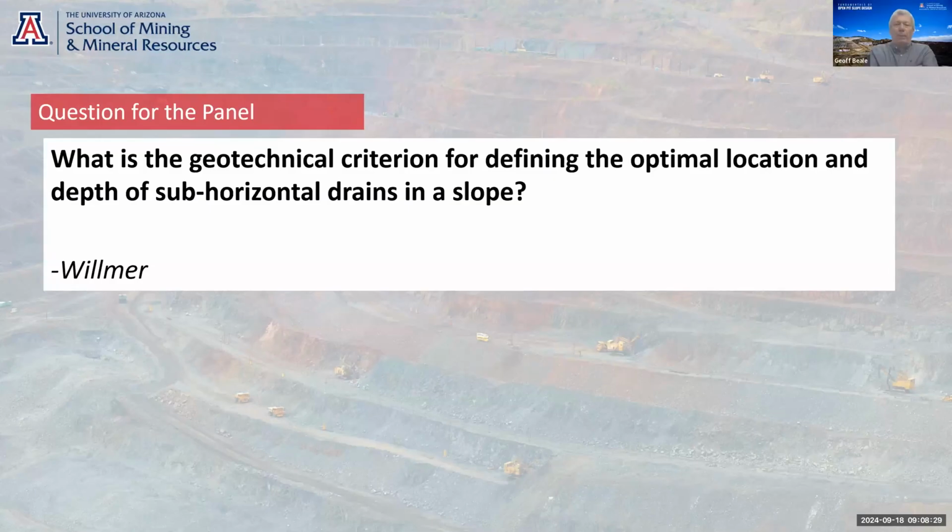So again, I think we hammer the point to make sure your piezometers and your drain holes are focused on where you know, or where you anticipate, deformation in the slope to occur. And if you think about a failure surface, the only thing that failure surface sees is the pore pressure actually on the failure surface. So if you've got a failure surface that's let's say 100 meters behind the slope, then if you drill the drains at that failure surface at 100 meters, you're getting maximum benefit of those drains. And if you drill 200 meters, the only thing that the failure surface will see is the removal of pressure at 100 meters at the failure surface.